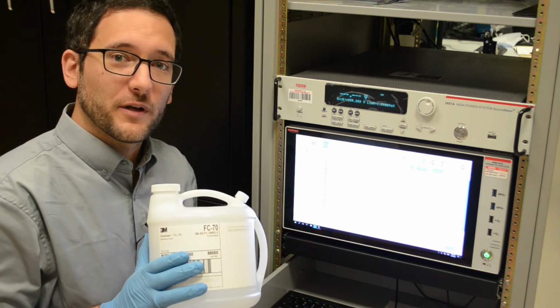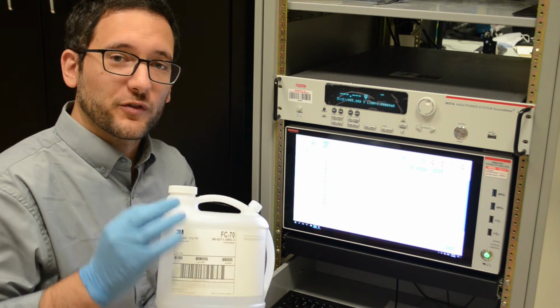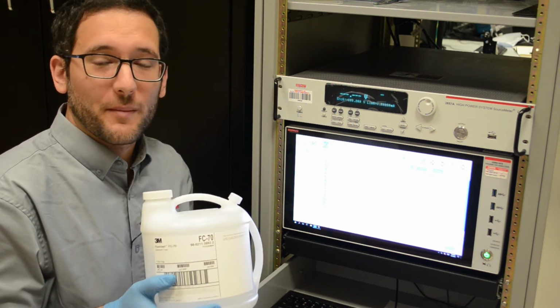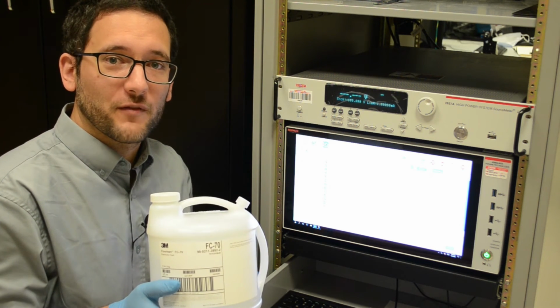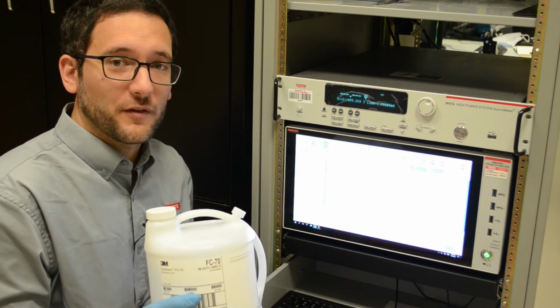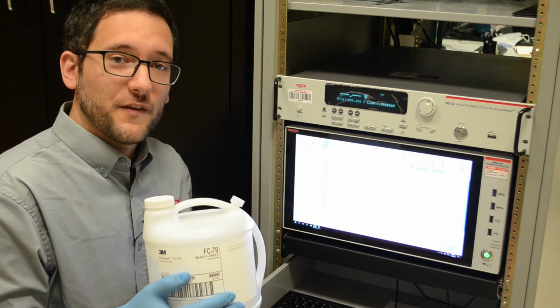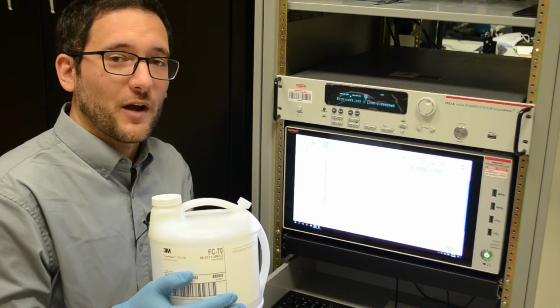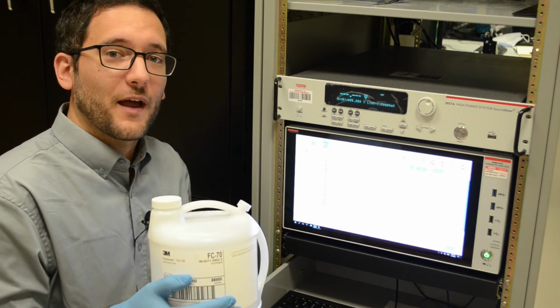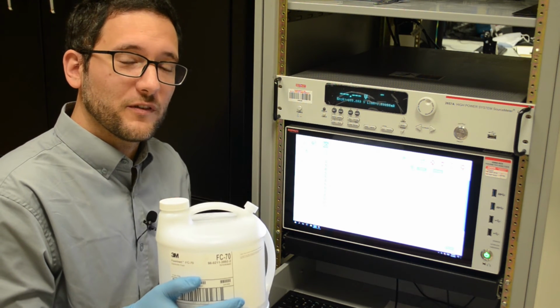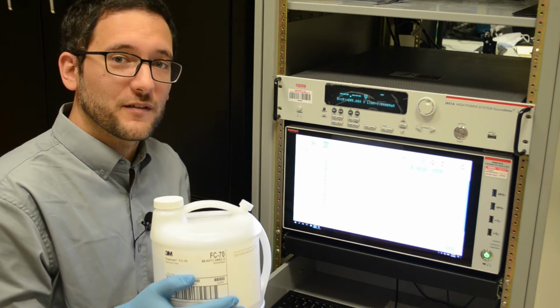This particular liquid is called Fluorinert, and we would extract a droplet or two, or maybe even an entire volume that would surround the wafer, so the wafer is immersed inside of it, and we would probe through the liquid onto the pads as we did earlier. This liquid, Fluorinert, does not break down until very high voltages, and so it would ensure that any breakdown characteristic that we see is really due to the device itself breaking down.